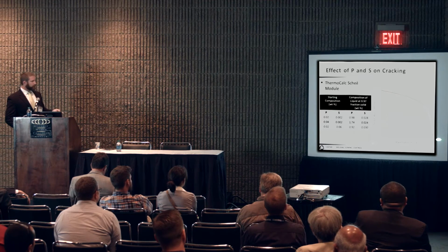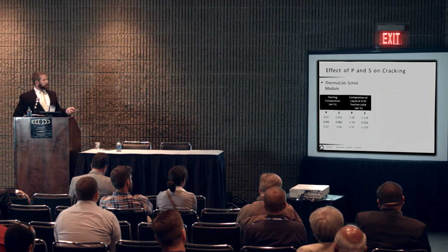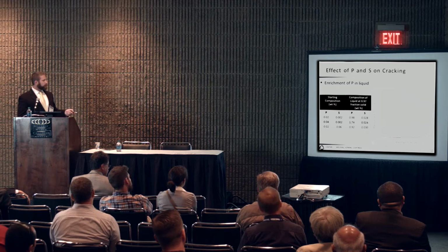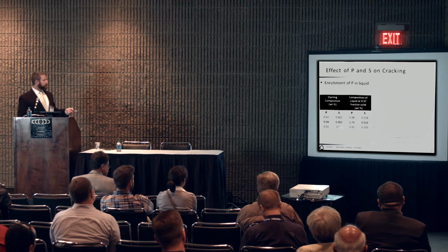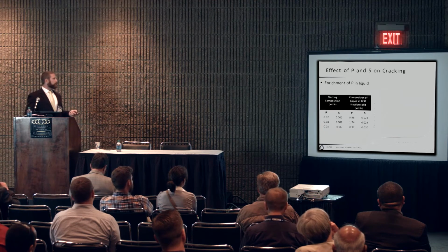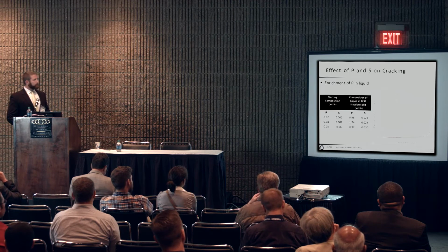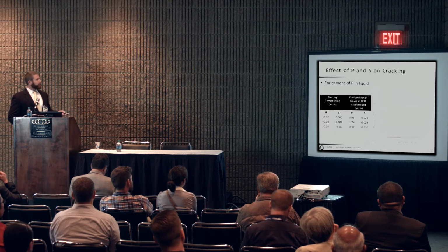So this is just temperature versus fraction of solid with our different phases to form. And again, this is primary austenite solidification, so we go to liquid plus FCC, and then liquid to FCC plus manganese sulfides. Looking at phosphorus by itself for this min phosphorus, high sulfur alloy, the third alloy in the table, as we'd expect with a typical Scheil simulation for a partition coefficient less than 1, we just see continuous enrichment in phosphorus of the liquid.